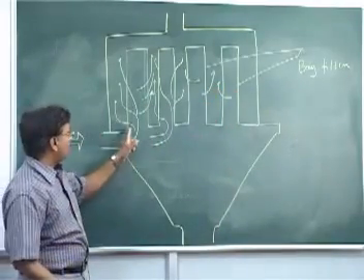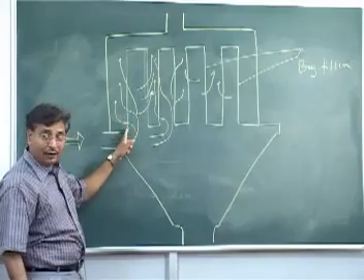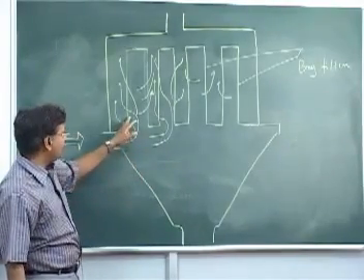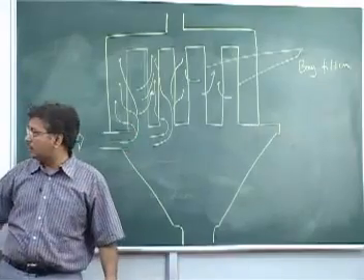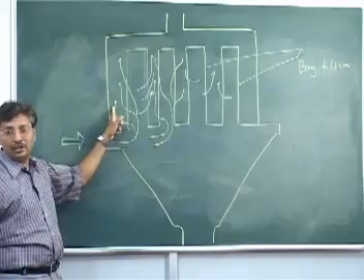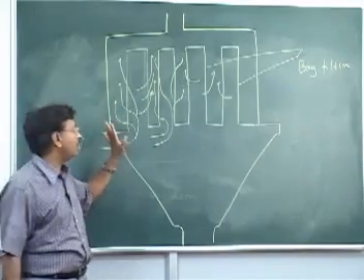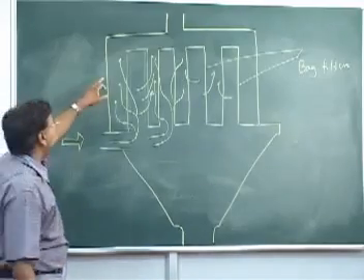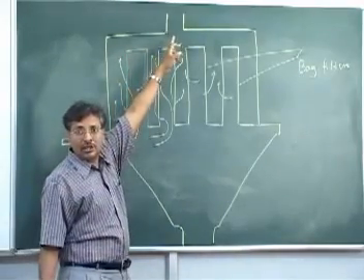See? So what will happen? This is your fabric filter, like cloth, a special kind of cloth, and so the particles will be stopped here because of some of these mechanisms, and your clean air will come out. Again, we are just talking physics, we are not talking mathematics here. So then finally you will get the clean air that will go out from here.